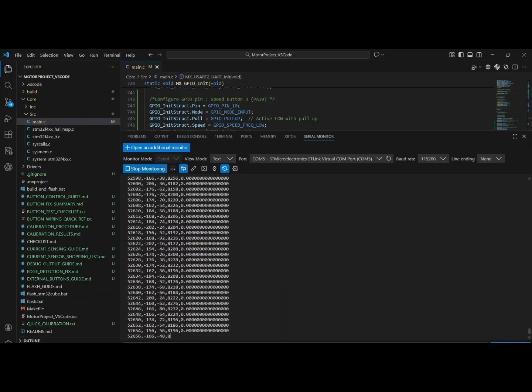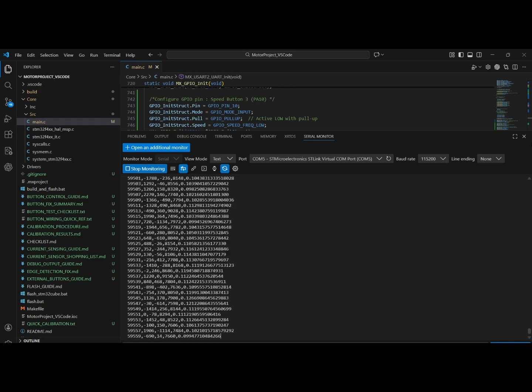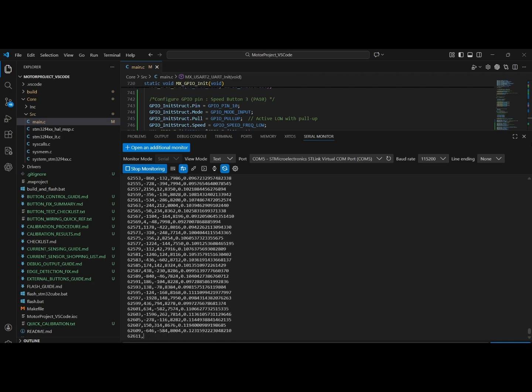Sensor data are acquired continuously and transmitted to an external system using UART with DMA, enabling efficient and non-blocking data transfer. By using interrupt-based control, DMA-driven communication, and a structured main loop, the embedded software achieves reliable real-time motor operation and data acquisition without an operating system.